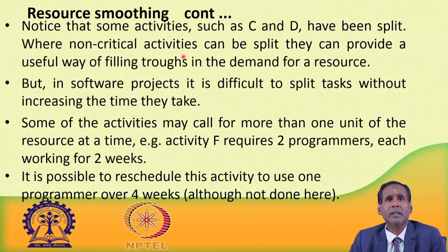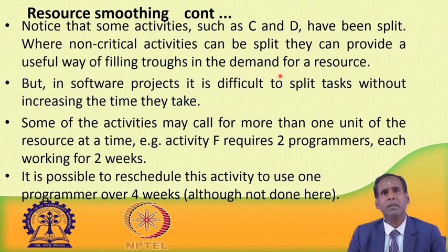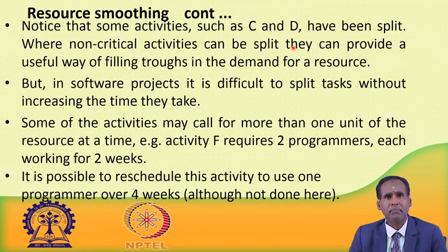Where non-critical activities can be split, they can provide a useful way of filling troughs in the demand of the resource. So, please remember, do not try to split the critical activities. Only the non-critical activities can be split. It will help in making the histogram of the demand for a resource even. But in subtle projects, it is very difficult to split the tasks without increasing the time taken.